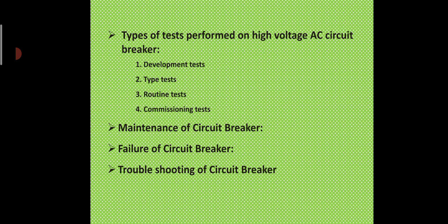Next is unequal wipe and contact travel when the breaker is open or the breaker is closed. Its possible causes are erosion of contacts due to frequent short circuit operations, wrong adjustment during maintenance. Its remedial measures are: check the contact strip, replace the contact if necessary, adjust the contacts if the length is unequal. Next is one pole does not close. Link of the pole might have broken, the contact of the dead pole has damaged much. Then remedies are: isolate the pole and carry out the repairs.